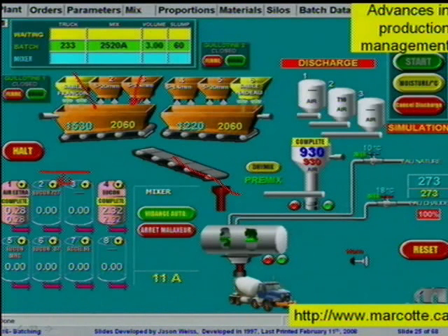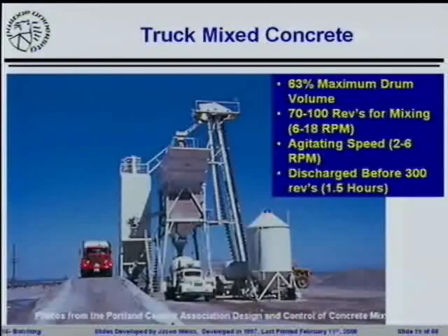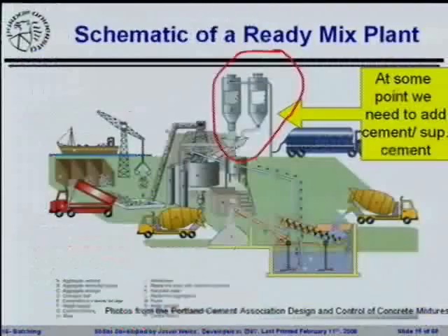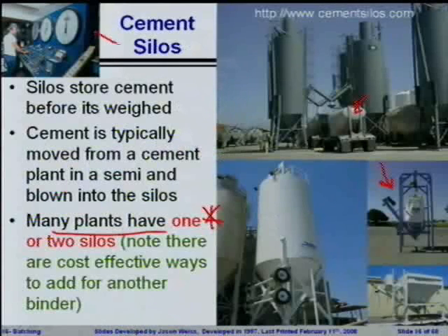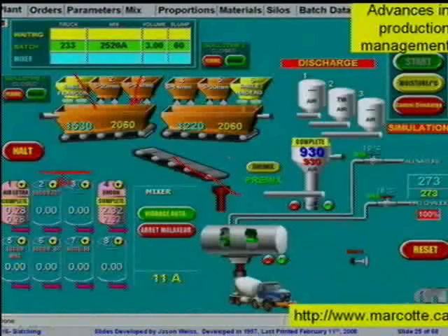They can call up a particular mixture proportion. This will be preconditioned to weigh out those materials, add them in a specific sequence, and place them in the back of the truck, which is a little bit different than what we've seen on a lot of the other pictures. I'll jump back to this type of schematic, where we see up in the top left-hand side this person who's running the plant actually using these controls down here to open and close those clamshells. These are the scales of the different materials that are being weighed out. A lot of that is going away, and you're seeing a lot more producers moving toward this type of operation.